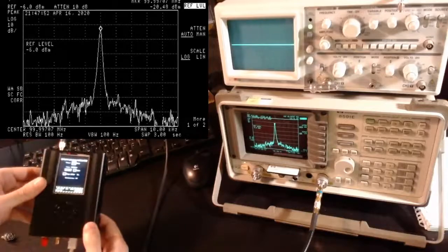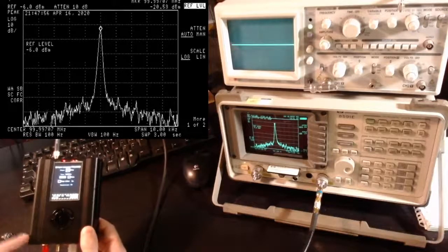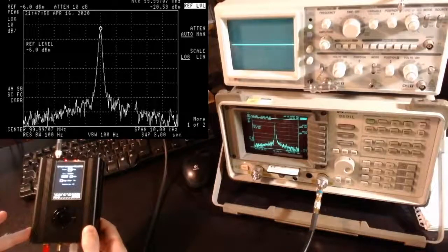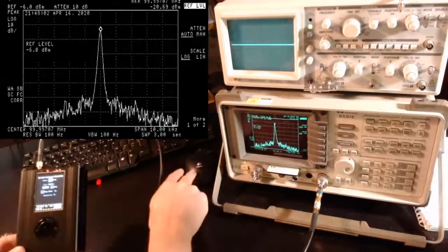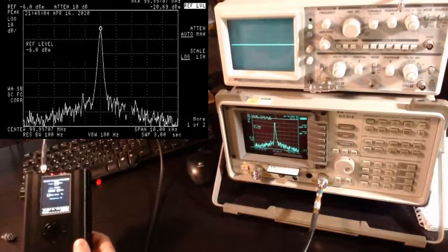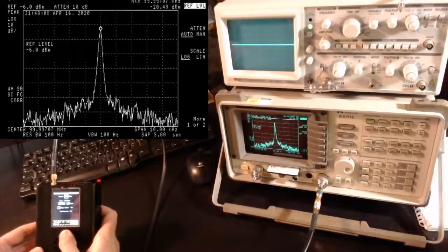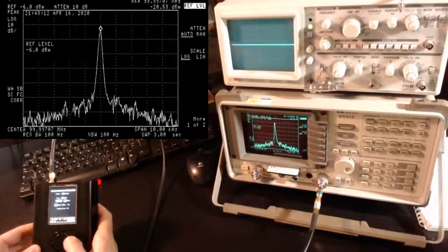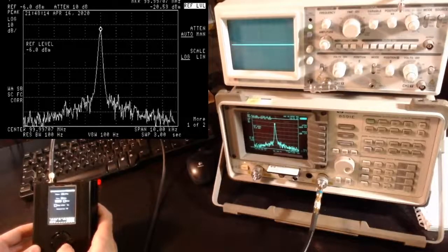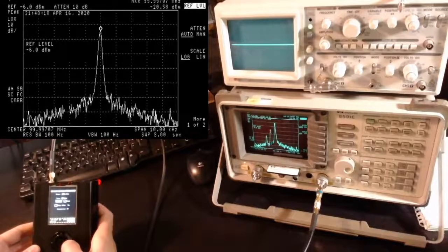It's expected because this clock is not temperature compensated. I mean, the oscillator is not an oven temperature compensated oscillator. So anyway, that's good enough, and there's not a problem, at least for me in this context. Now, instead of just producing a pure sinusoidal function, I'm going to produce an FM modulation at 1 kilohertz. So let me do that.